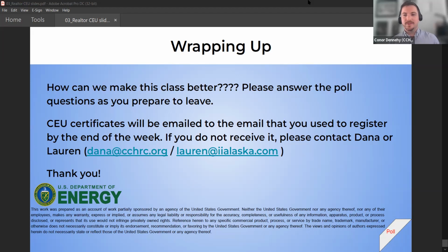You got to steer people away from that, because we need that airflow to come out, because it's got to suck in air from the top and distribute it from the bottom. So we got to keep some clearances, which the manufacturer has spelled out in the user guides and manuals. And likewise on the outside, a lot of people don't want to look at those either, and so they want to cover those up. It's very important to make sure that there's enough airflow around these systems so we can get adequate air exchange, because people come up with some nice architectural screens, they put them over them, it looks great, but it'll kill the unit.